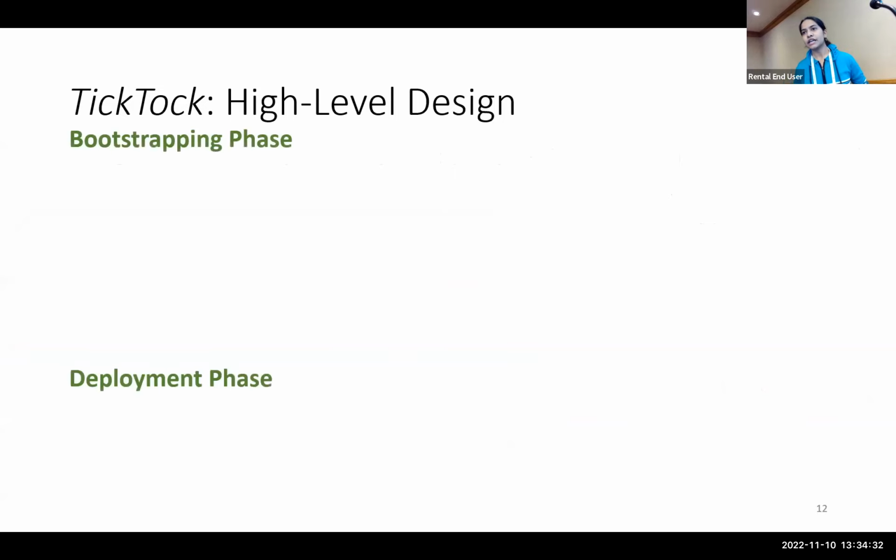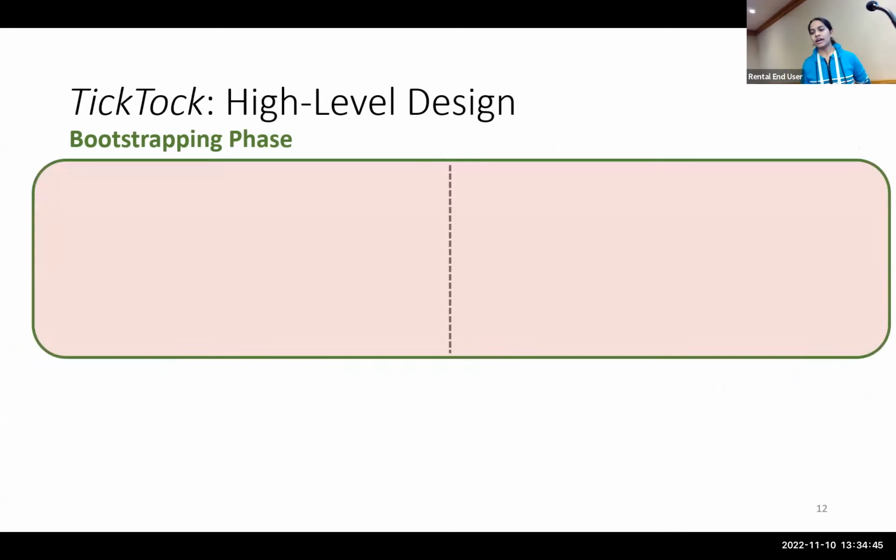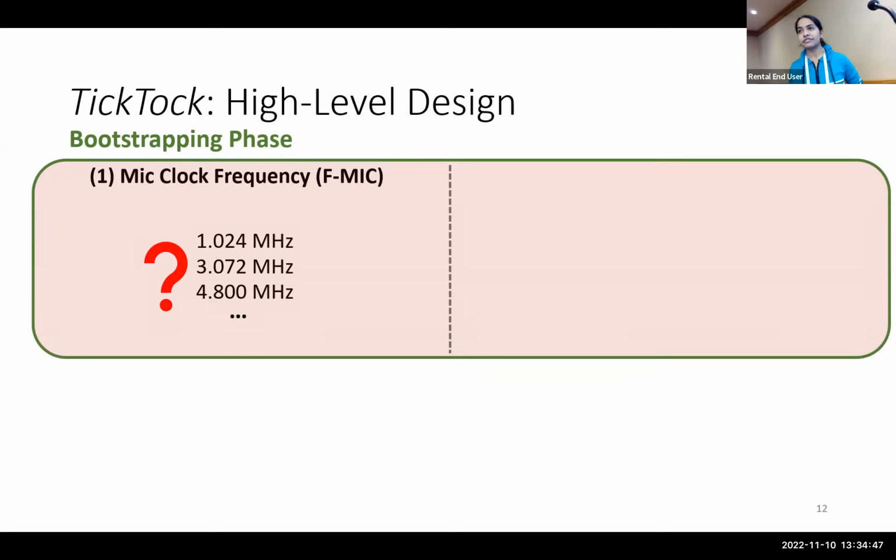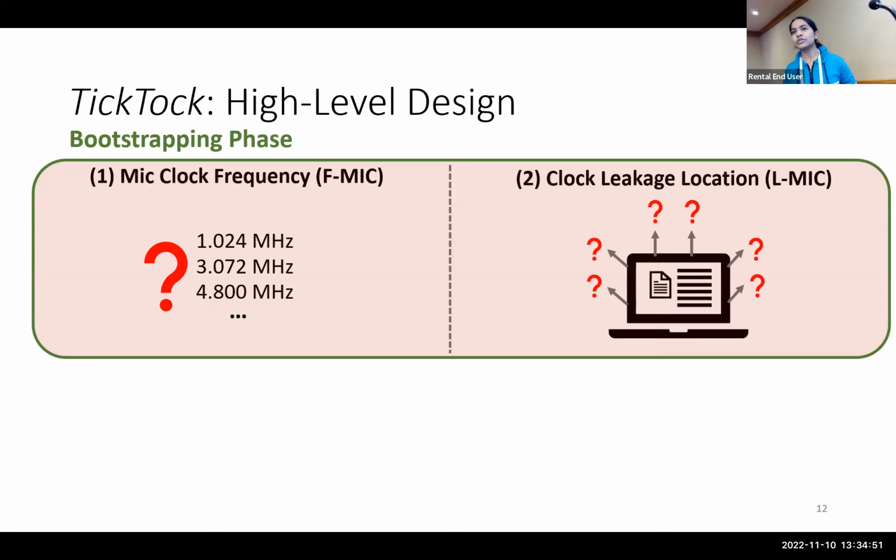So now that we understand the key idea of TickTock, let's go into a high level design. So TickTock consists of two phases, the bootstrapping phase, where we try to learn the unknown parameters, and the deployment phase where we perform the mic status detection. So in the bootstrapping phase, we try to identify what is the exact microphone clock frequency we're looking for, and also the exact leakage location on the external of the laptop. And both of these are laptop model dependent.